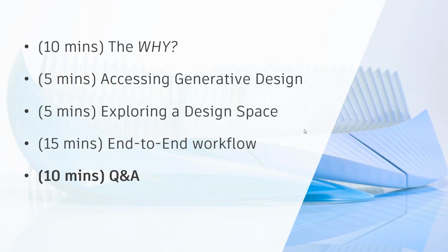No, I mean, we had a couple good questions. One was around whether the outcome produced from generative design was associative to the originating Inventor part, and the outcome itself isn't. If you modify the original Inventor part, the outcome will not update as is.